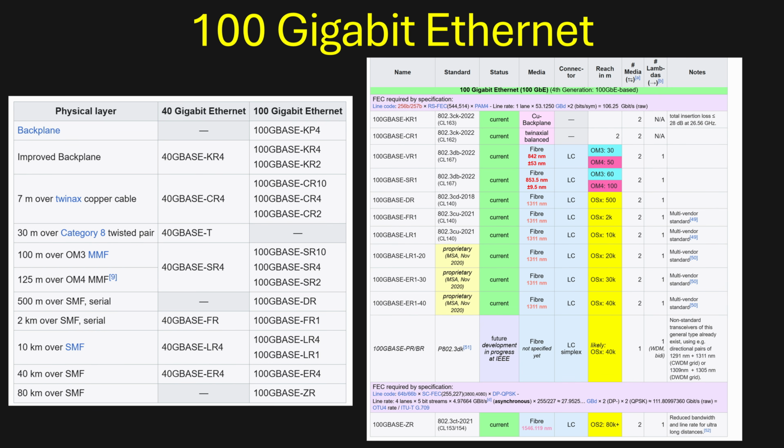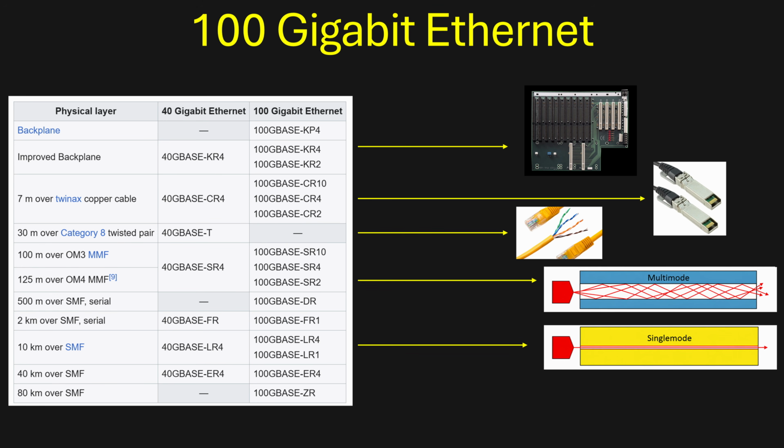use copper only in the form of traces on PCBs and different kinds of copper cables. Copper is preferable for short distances because computers natively use electrical signals, so with copper cables, there is no optical to electrical conversion required. However, beyond a few meters, the electrical resistance of copper is not acceptable for modern high bandwidth standards. This is because the electrical resistance and noise is very high when transmitting a very high bandwidth signal.